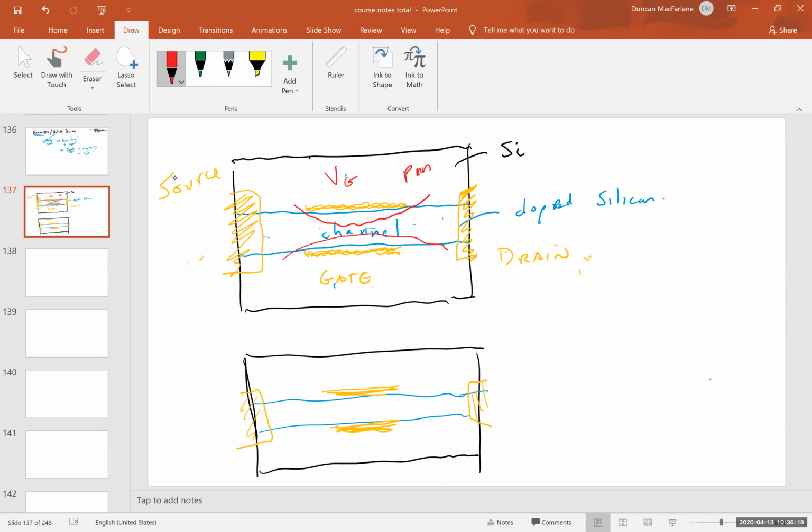The voltage applied to the gate can pinch off the channel, and pinching off the channel is a very descriptive phrase. It's not just gobbledygook vocabulary. It stops current flow. So depending on the voltage, I can either have current going through or I can stop current from going through.